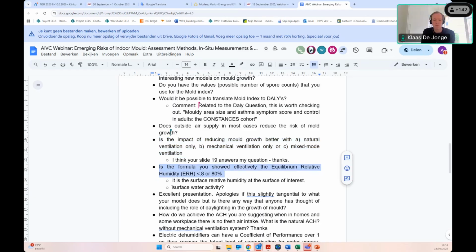So the Finnish mold growth model takes relative humidity at the surface and temperature at the surface as input. In the model, what I did is I coupled a very small EMPD model. Well, small in the sense that I assumed it's only a small surface area of the whole space.